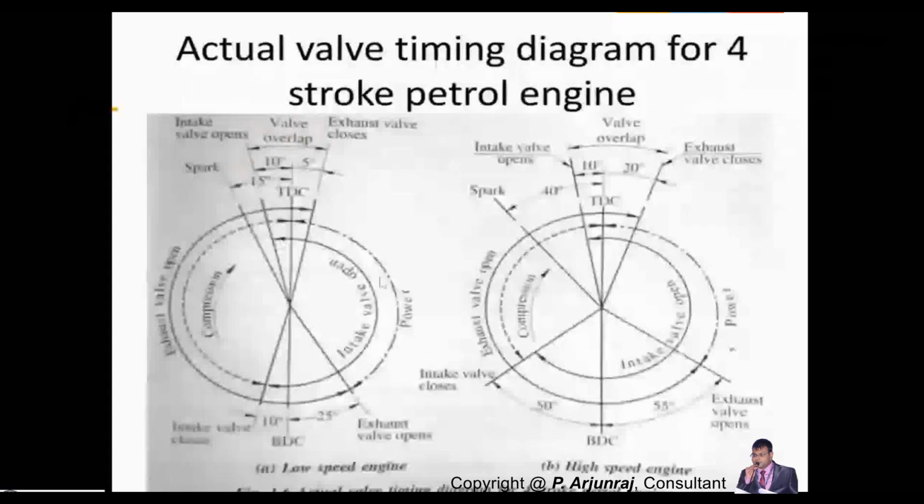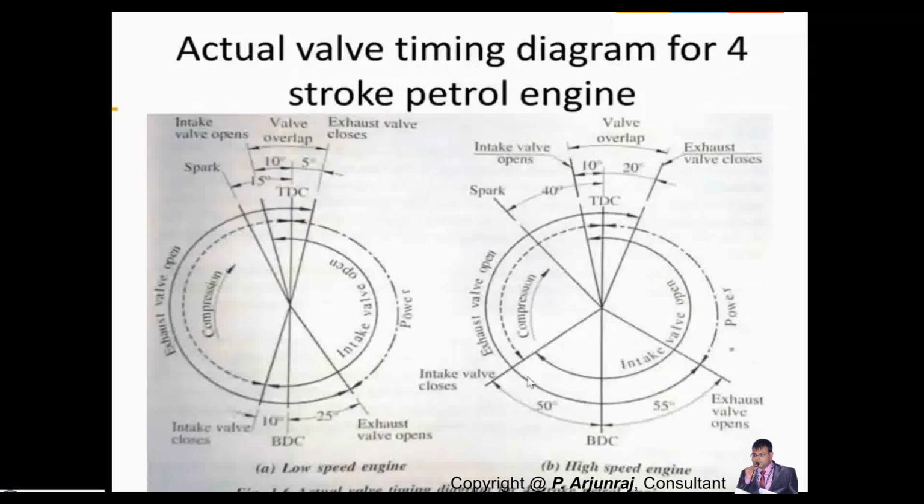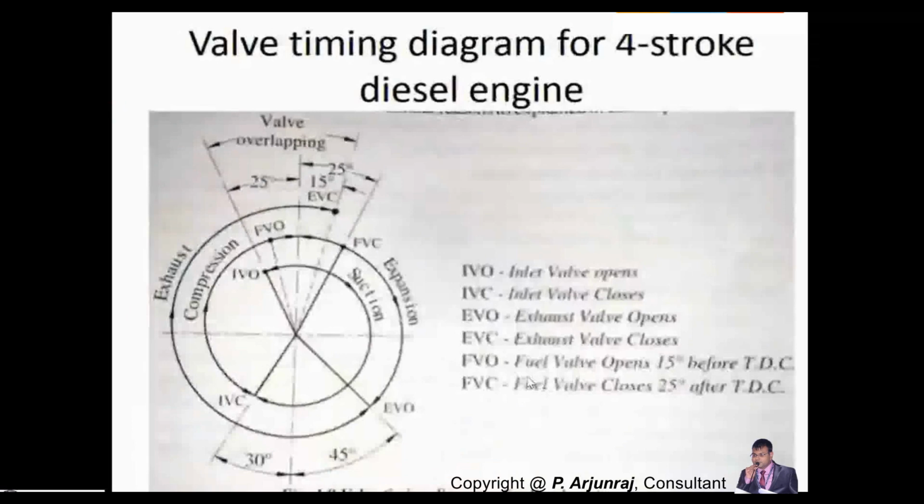You need to understand the concept and try it as per this. It is very important. You also need to see the valve overlap and mention all the criteria. In the case of the four-stroke petrol engine, the valve overlap is again based on the inlet valve opening and the exhaust valve closing. What are the overall degree values? You need to draw it in a very careful manner, and it is based on the four-stroke cycle I explained in the first class.